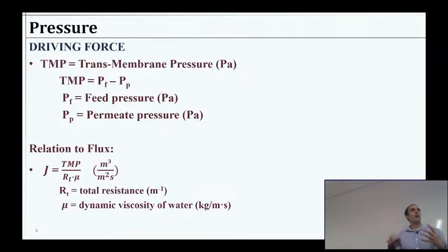And in the same way, a membrane, based on how big the pores are, will allow or prevent some amount of pressure. So we can push water through a membrane in that manner. And we'll call that pressure difference between the feed and the permeate our transmembrane pressure.